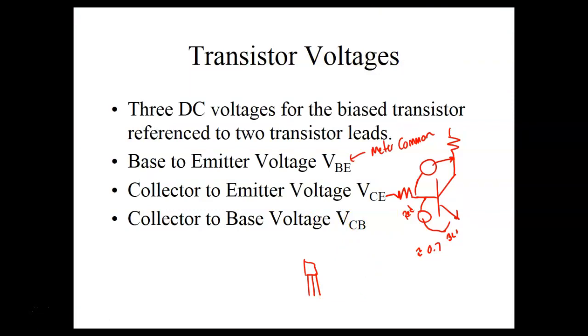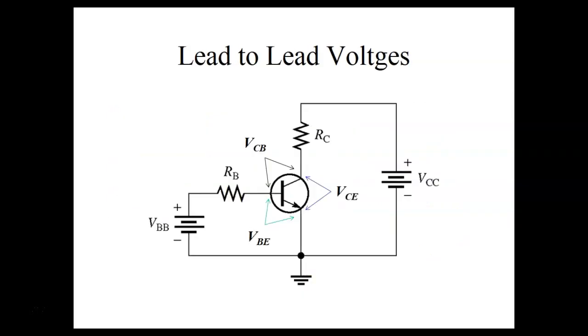So I've seen students twist resistor leads together to get a certain thing on a trainer, where they could just hook them in the same hole, right? So here's our measurement. Like I said, I don't have to get on that little tiny lead on the base. I can get on this resistor right here, and I can get on the lead of that resistor right there. And I would be measuring VBE.